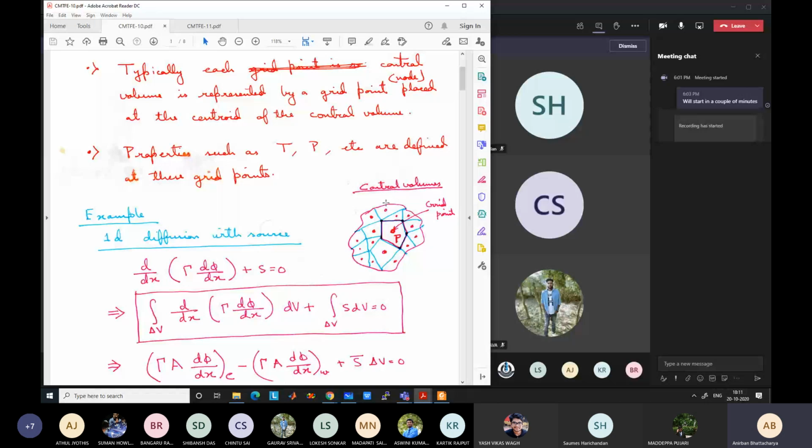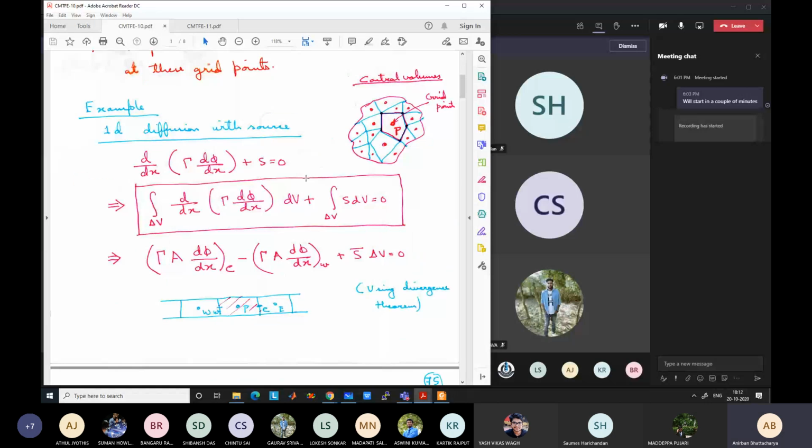Okay. The other important difference, although it is not apparent from the equations, is the way the finite volume method is done: you take a control volume. For the finite difference method, we only had some points, with no volume around the points, and we only had values at those points, and calculated our equations or derived our discretized equations based on those in a regular fashion, like going from i equal to 1 to some value, j equal to 1 to some value. In the finite volume method, we have a volume around a grid point, a volume in which there is a representative equation, and we integrate all the equations over this control volume.